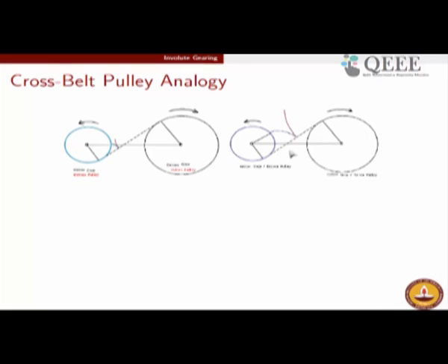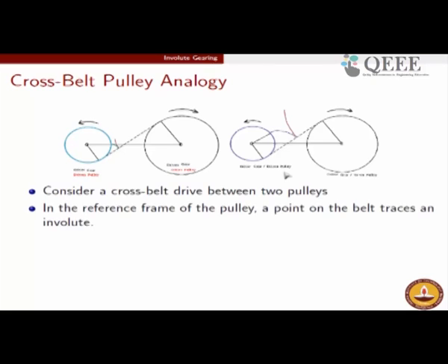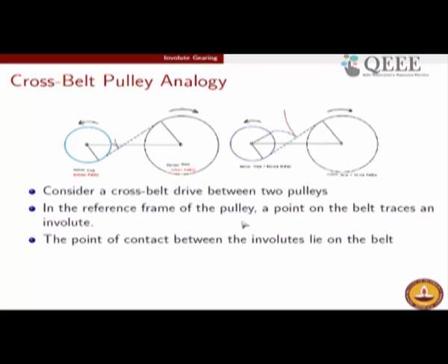So, therefore, the common normal is held fixed during the course of engagement of two involute tooth profiles, which is exactly what we have seen even in our experiment a few moments ago. So, therefore, we come up to this very important conclusion that the common normal has not changed. So, this is exactly what I have told you.